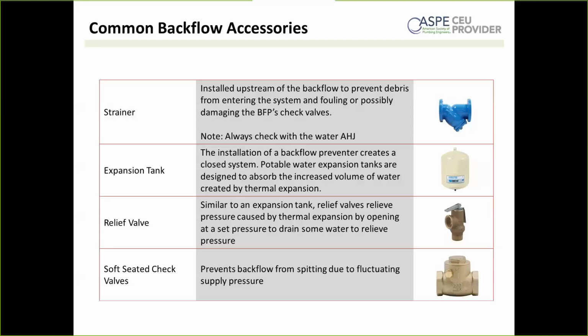Also, it's expensive to repair. So if you're going to have a closed loop, a relatively short run of piping, in some sort of situation where you're going to get that thermal expansion, please consider an expansion tank or relief valve.